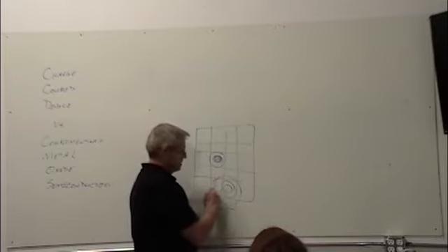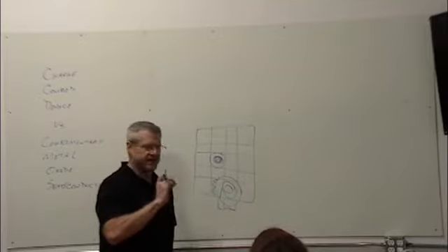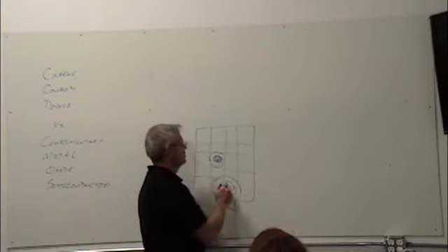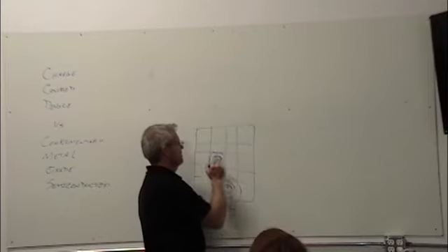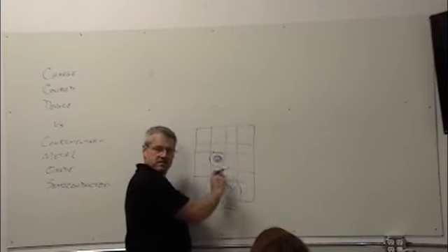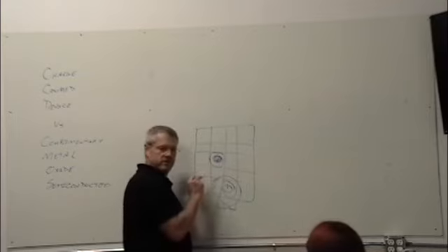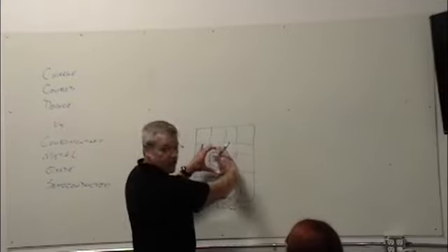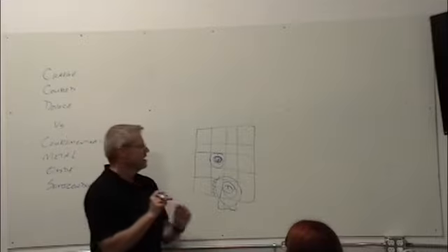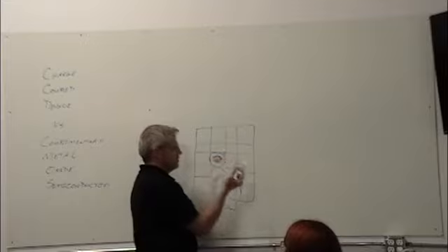But I've got these partially blacked out, so I look at a point source and I calibrate this and I say, oh, well I see this much energy here and I see this much energy here. That starts to tell me things about the position of this in this 2D space. And if I want to, I'm basically making a little pinhole camera, a micron-sized pinhole camera right on the surface of my imager. And I can start playing a game where it's called a coded aperture.